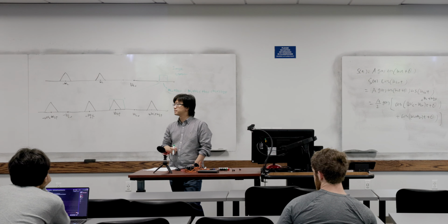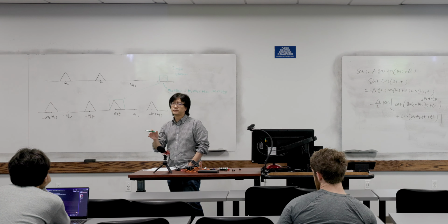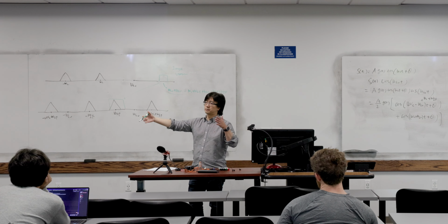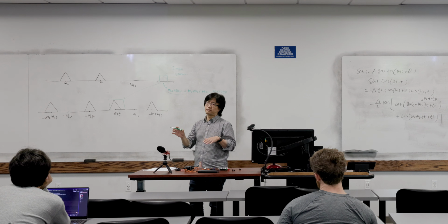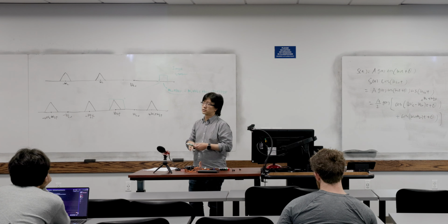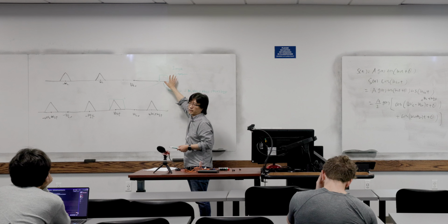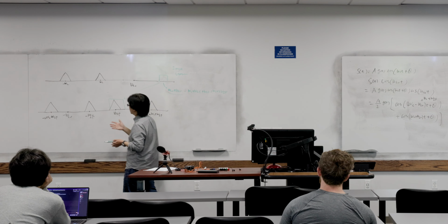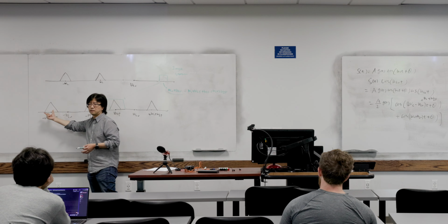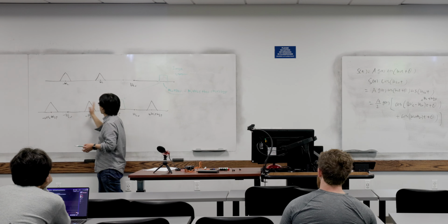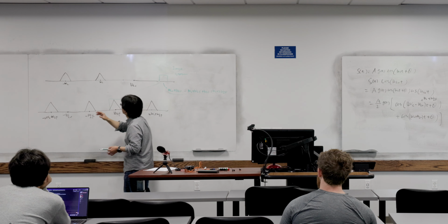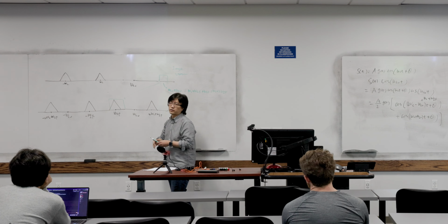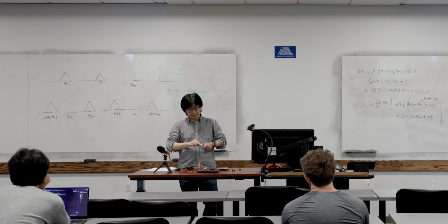Yes? You can maybe run it through a bandpass filter first. Exactly. We just run another bandpass filter with a certain bandwidth, but we don't need a very high quality of that. So we filter this part out. We only need a certain frequency, because remember, we have a very high quality filter around here. So anything outside here doesn't matter. We filter out this part, and then we're fine. That's basically the solution.